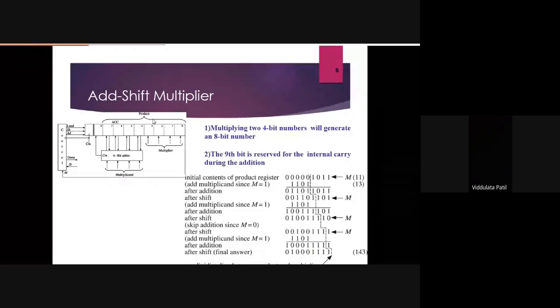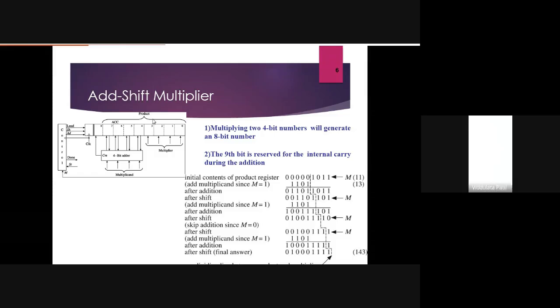Okay, so now go for the accumulator. So have a 9-bit accumulator and in the last 4 bits store the multiplier. Okay, now what is the last bit? Now we are considering 1010 as the multiplier. Whether my screen is visible?